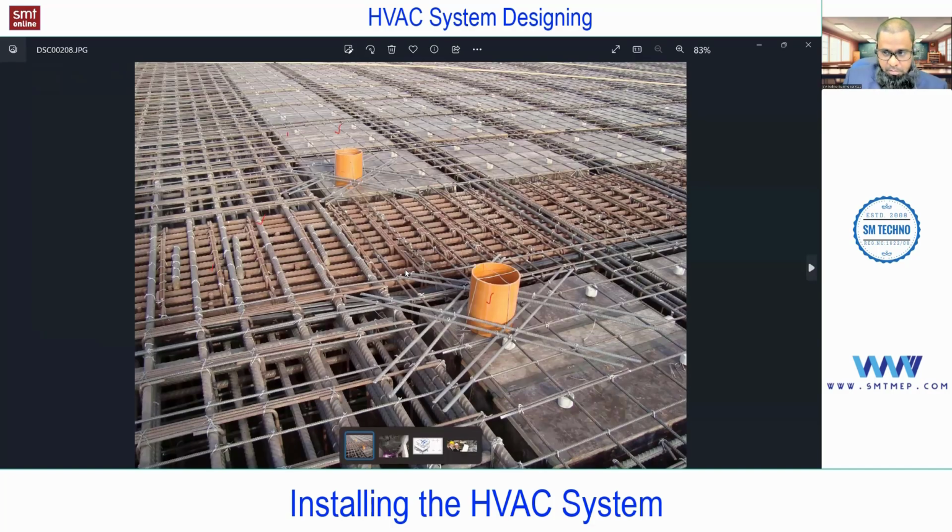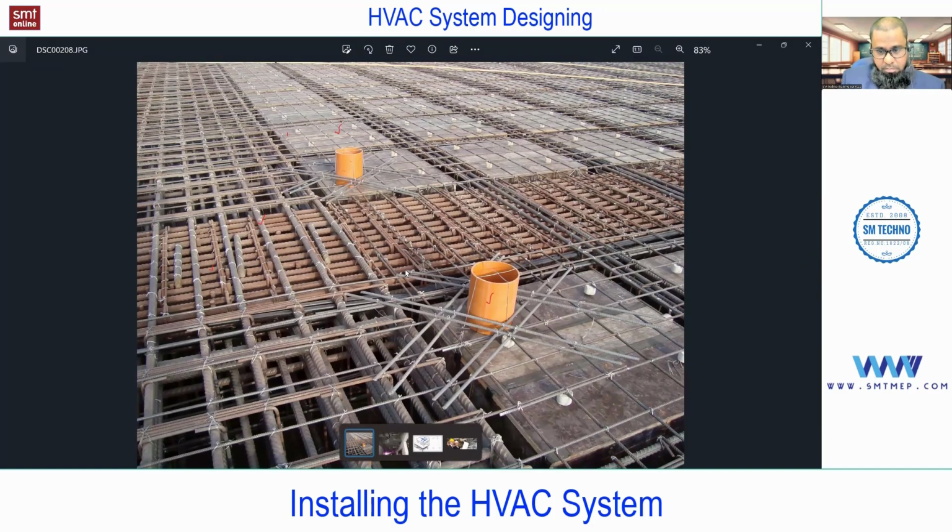For that also, you're talking about this, right? It's a vertical sleeve in the slab, but I can see the horizontal sleeves on the beams. You'll find the sleeves in the beam, column, or even in the slab. So it is allowed, no issue. But at the design stage only. Later, after completing the structure, they will not allow openings, or they are not allowed to disturb the structure.